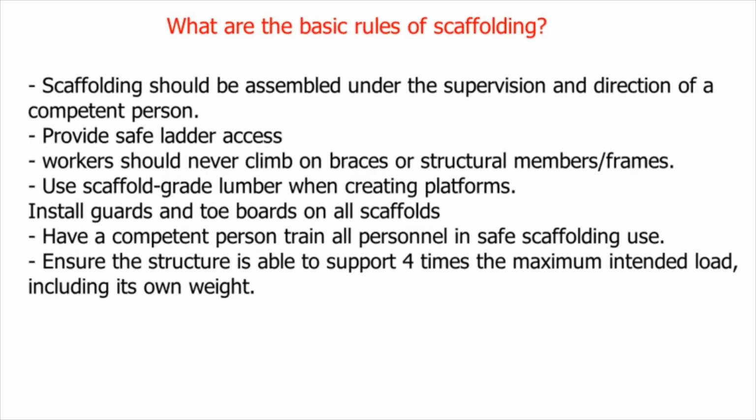Scaffolding should be assembled under the supervision and direction of a competent person. Provide safe ladder access. Workers should never climb on braces or structural members, frames. Use scaffold-grade lumber when creating platforms. Install guards and toe boards on all scaffolds. Have a competent person train all personnel in safe scaffolding use. Ensure the structure is able to support 4 times the maximum intended load, including its own weight.